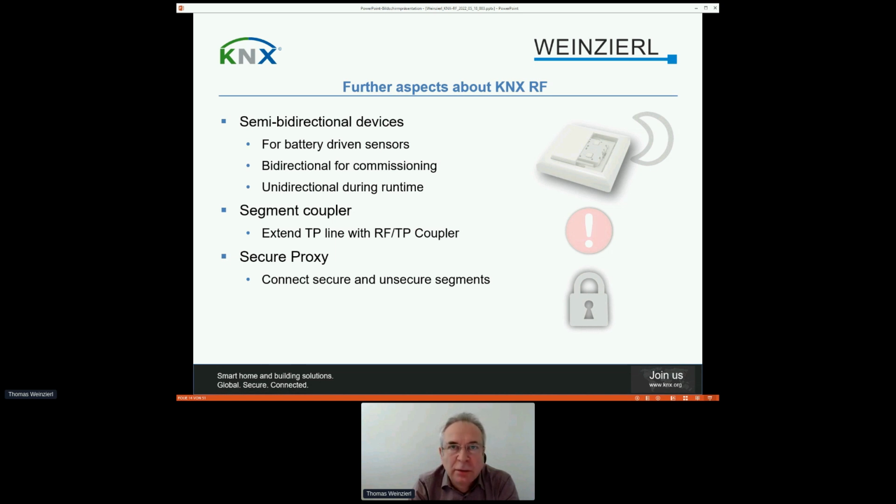So when ETS is doing the download, there's of course a lot of interaction between the ETS and the devices. And therefore the devices stay for a couple of seconds in bidirectional mode, but afterwards they go into sleep mode and they act unidirectional during runtime.